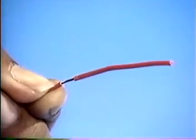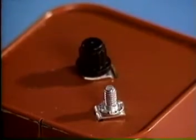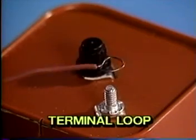Once you're set, squeeze the strippers. This cuts the insulation, but not the wire, allowing you to slip the insulation off. To connect the wire to a terminal, you must form a terminal loop on the ends of the wire.